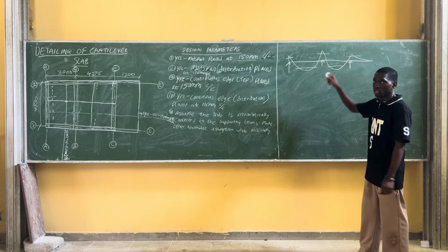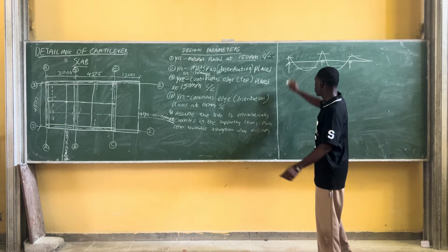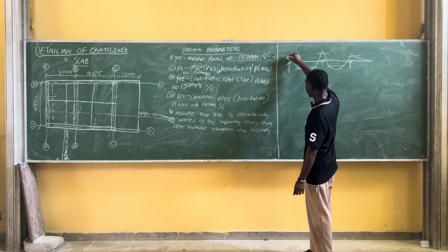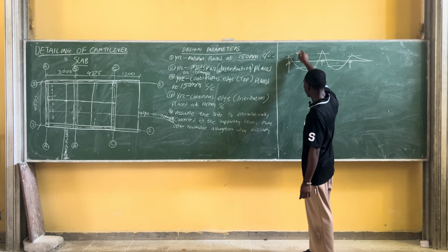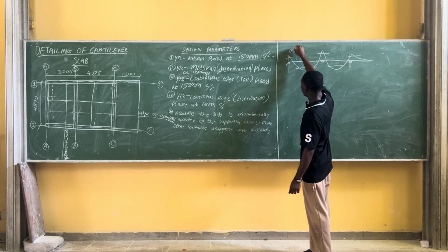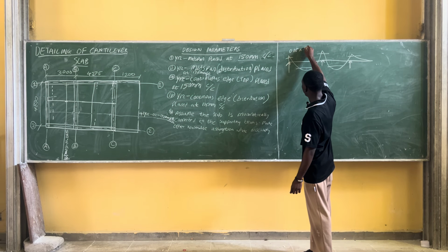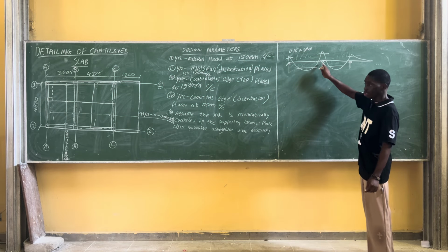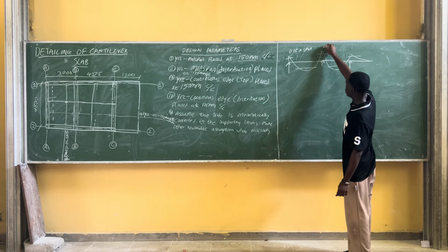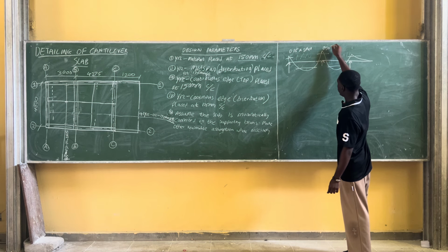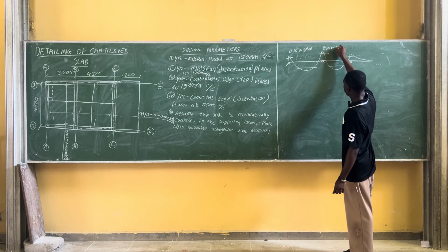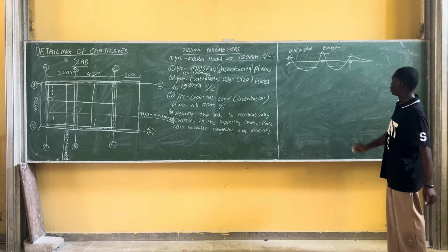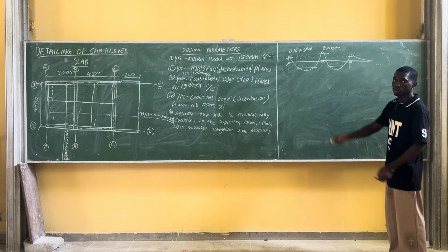Those are the ones that need critical support. So Bronson asks, what is the length here? What you are getting for this top distribution bars that we actually need is 0.15 times the span. While here, this middle span is 0.3 times our span. The same thing applies to this.